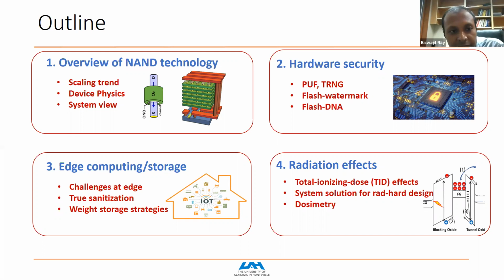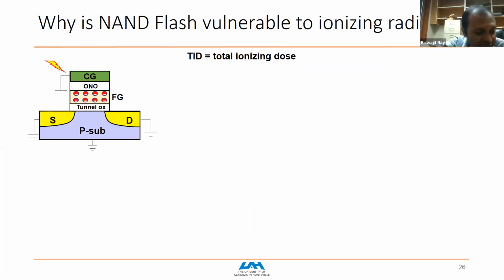Okay. So these commercial flash memories are not designed for extreme environments. These are designed for terrestrial, normal user applications, so radiation tolerance is not a concern. When I was in the industry, we never did any radiation reliability testing because it's not a concern. The usual radiation that you go through in an airport X-ray scanner will introduce errors, but you always have error correction in the system. So the system will correct all those errors, and that's why we don't care much on the radiation side.